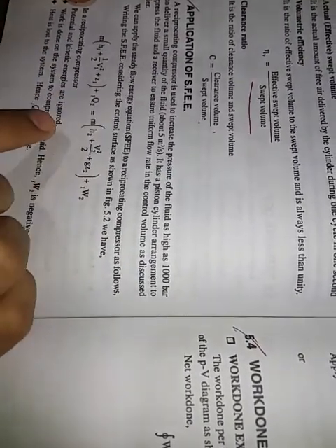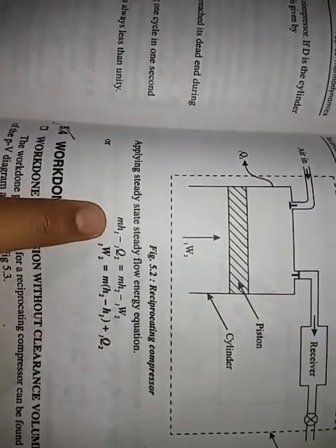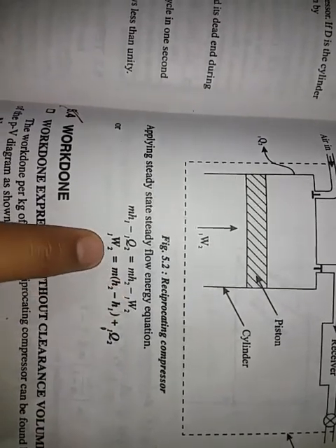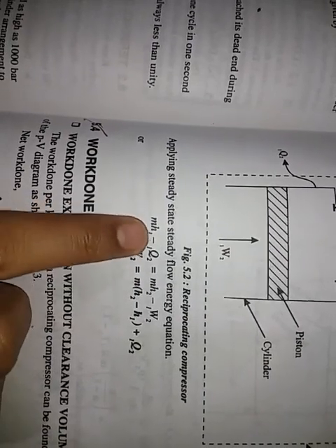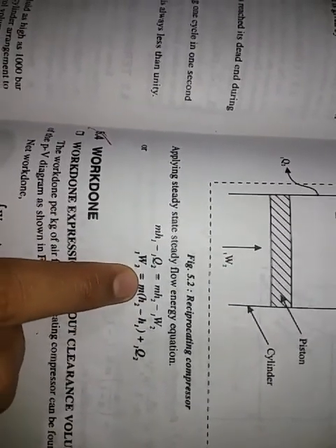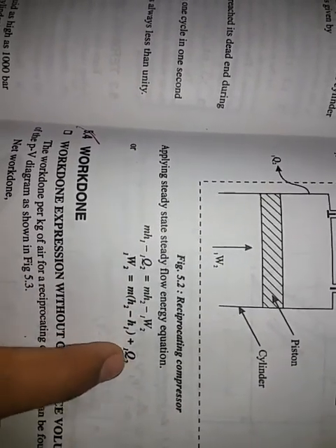Now we know that heat is rejected by the system, or rejected by the air, so I will take heat as negative, and we are supplying work to the compressor, a work absorbing device, so W12 will be negative. Now if I apply this, what is remaining? m h1 minus Q12 equals m h2 minus W12. So what will W12 be? W12 equals m, which is constant, into h2 minus h1, plus Q12. What is m? m is the mass of the air, h2 minus h1 is the change in enthalpy, plus Q12 is your heat.